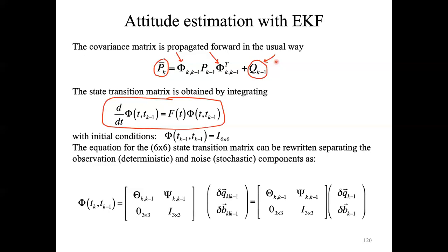But you have to be careful because, as I said, since it is a random walk, you don't have any guarantees that in the next period the gyroscope will behave the same. So usually you use, for example, scale factors in order to inflate Q, to be sure that you are not overweighting your gyroscope's measurements. Okay, so I hope that answers your questions.